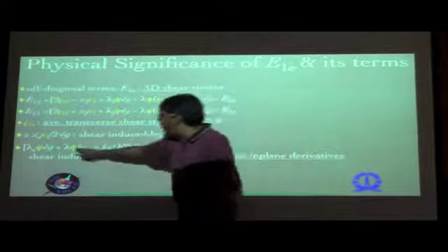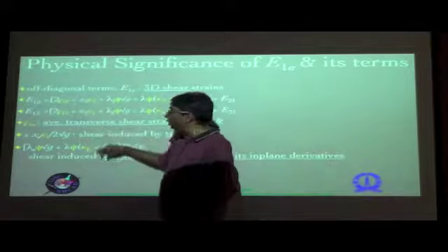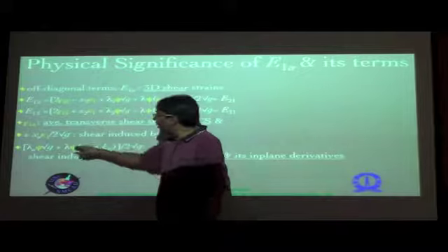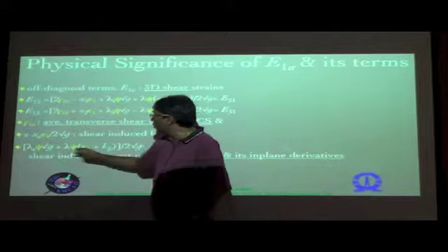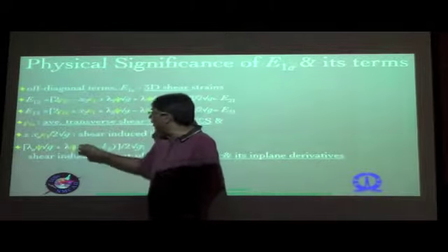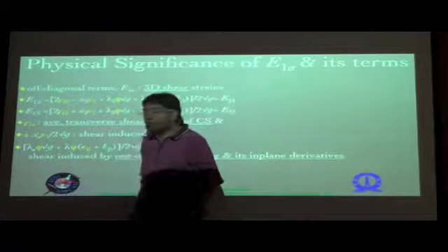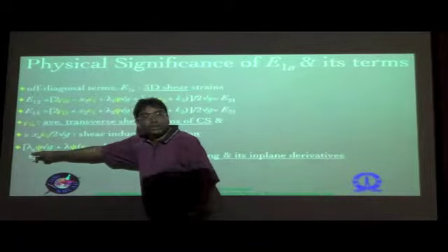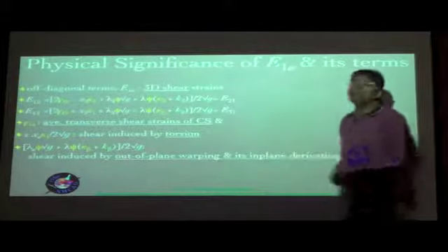So again, you see this is basically the out-of-plane warping, which multiplies the total curvature because of the initial curvature and the bending that is there. And so once again, you see that it's a small contribution multiplied by another small contribution. So once again, typically this is small compared to, for example, the contributions from the torsion. Similarly, you have the derivatives of the warping with respect to the cross-sectional coordinates, which is also contributing towards the shear strains, the 3D shear strains of the beam.